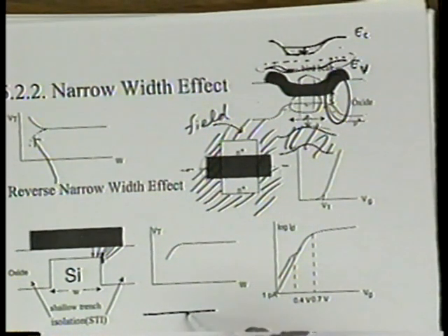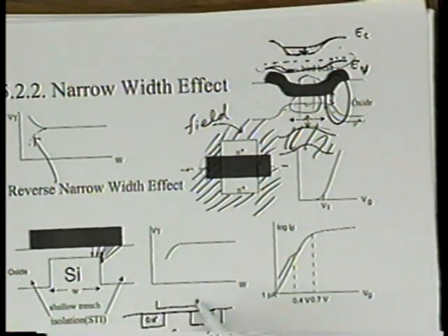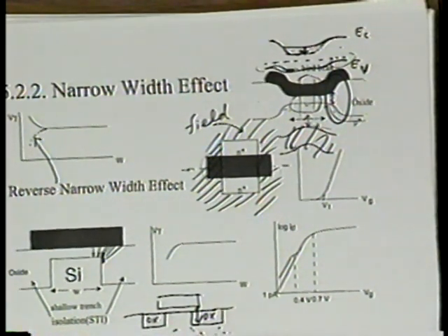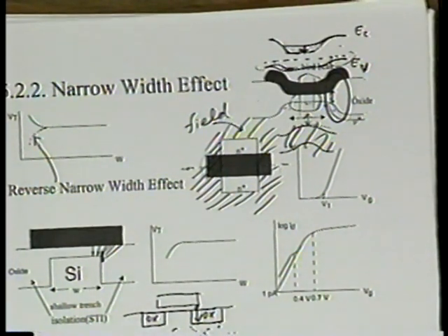That is, you actually start with a silicon substrate. You would etch some of the silicon away, all right? And skipping some of the details, you will then refill this trench with some oxide. And as a result, you end up with what you really want. That is, after you grow the gate oxide and put the polysilicon gate on, you will have a higher field threshold voltage because you have a thick field oxide. And if you wish, you could also implant this part more heavily, although it's almost not necessary these days because the well doping is already heavy enough, so the field threshold voltage is very high, and the active region threshold voltage is the 0.4 volt that you want. And this isolation technology is called shallow trench isolation. All right, the acronym is STI.